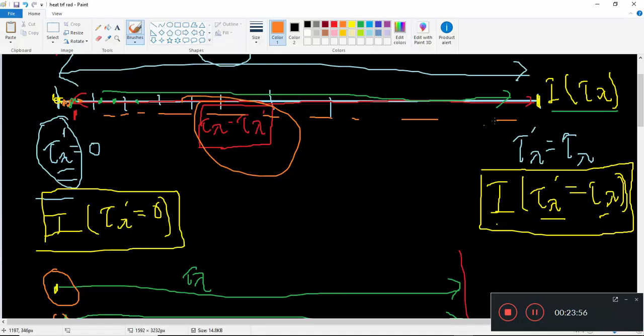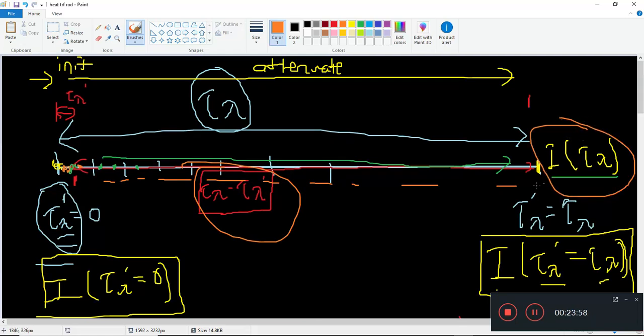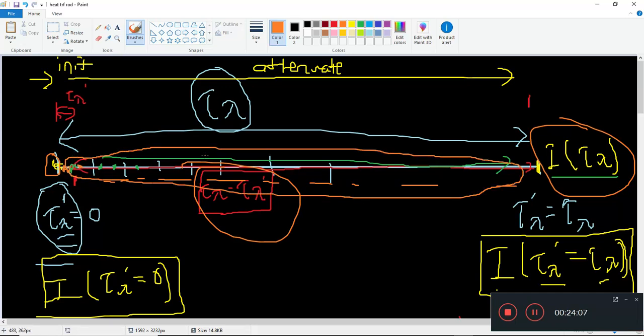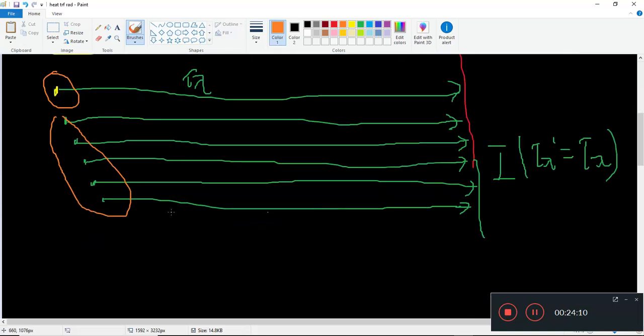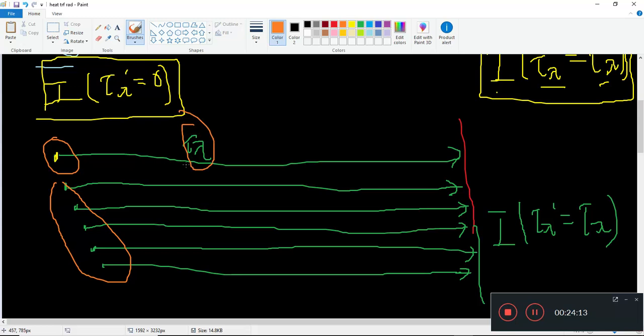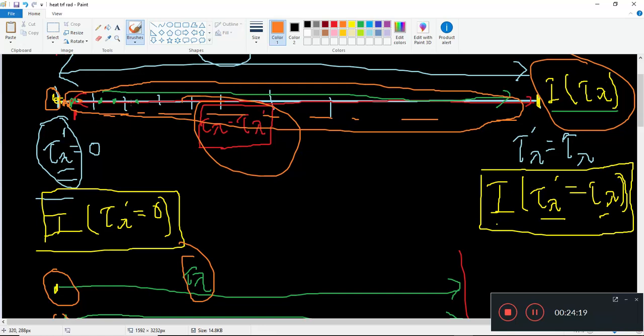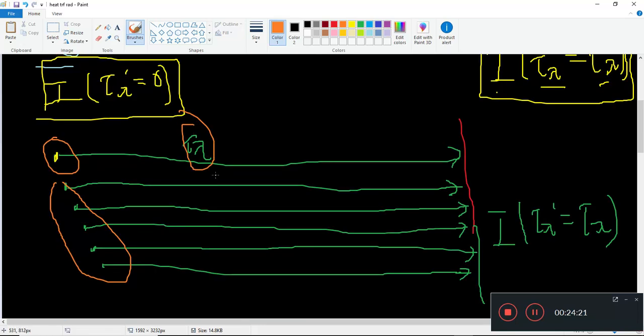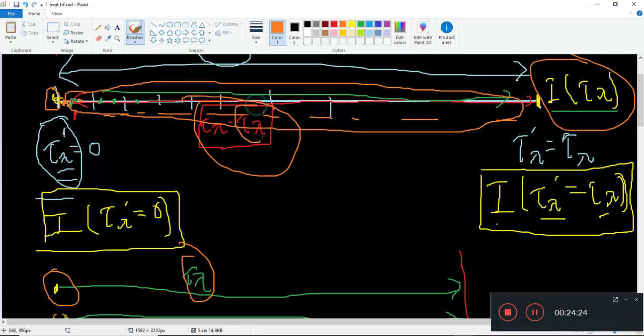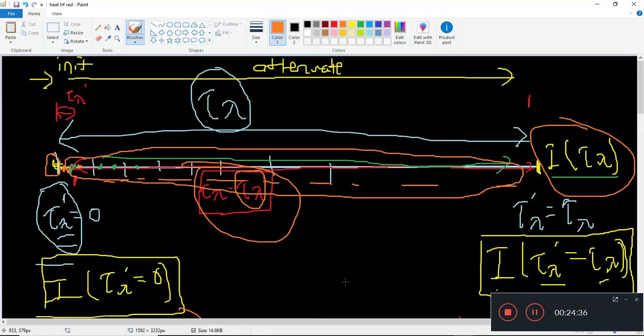So the intensity you see here, at the end of the day, is basically just the contribution of the initial plus the contribution of the source terms. That means the inscattering and the emission as you go through the medium. And it's all being attenuated through the respective optical distances. For the initial source it is tau lambda. For the radiation from each part of the medium, here it is tau lambda, and of course you subtract away how far it is from the beginning, which is this tau lambda prime. Hopefully that gives an intuitive feel of what this equation is trying to say.